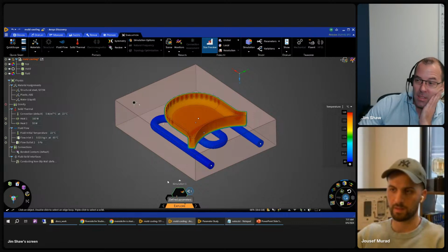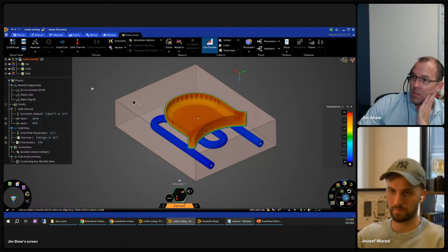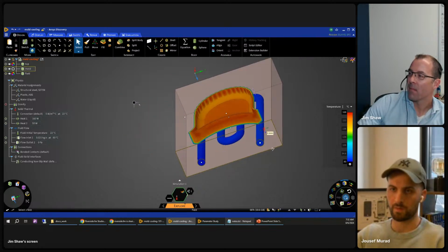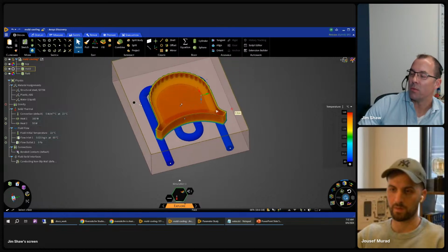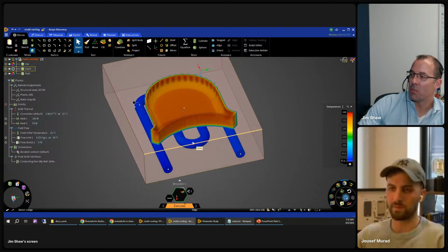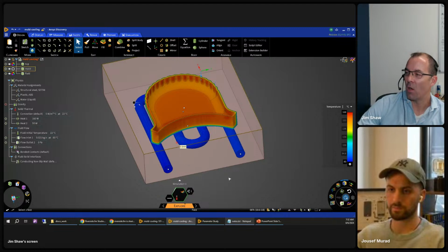Once we solve an analysis, we're never just done with one, right? As we say in our classes, you never hit solve just once. We're always iterating. Maybe you're iterating physics, maybe you're iterating geometry. So if I wanted to, from within Explore, while I'm solving, I can just go into the design mode right here. Just so that we all know what's going on here, there are two surfaces that represent the OD of the fluid and the ID of the mold channel. It's a nuance of channel flow: there are two surfaces in the CAD that we have to manipulate if we wanted to manipulate it.